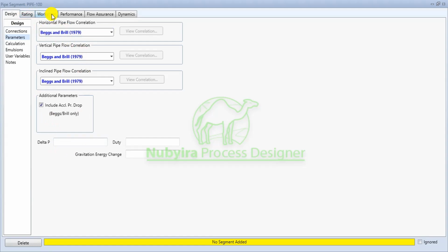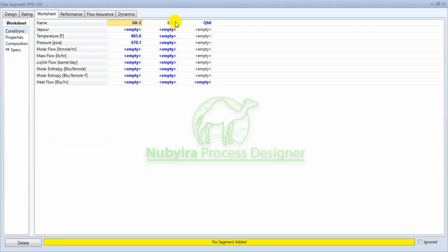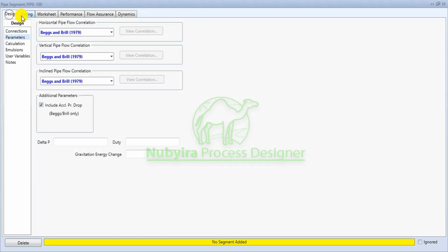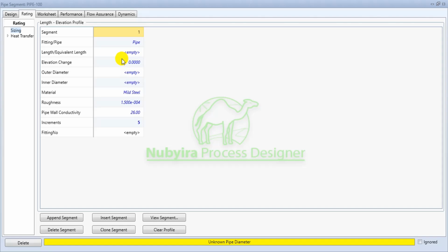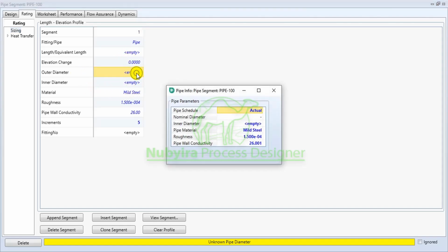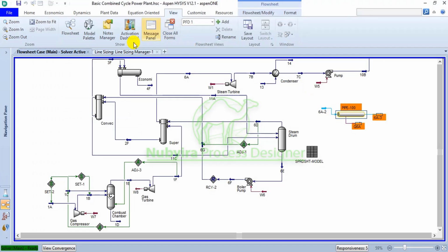So it's going to export the pressure drop, calculated to give the outlet pressure of the line. So you know the required pressure that will deliver to the line. That's the flow assurance aspect. Then you can rate the design by going to the section like what you have done, and specify the pressure that the line sizing you have specified for it. I think the line sizing is short for something. Let me confirm from the analysis.